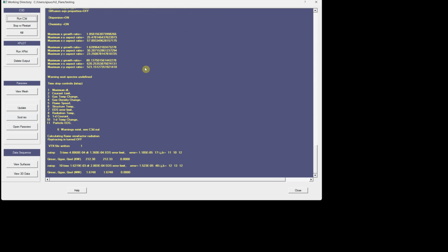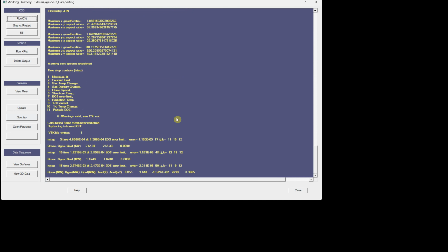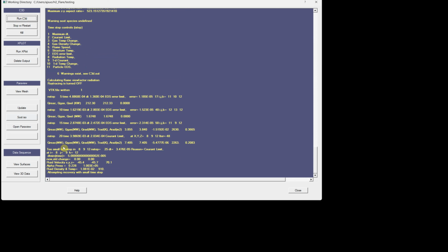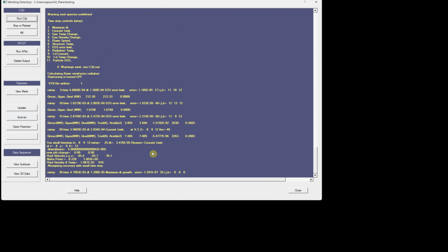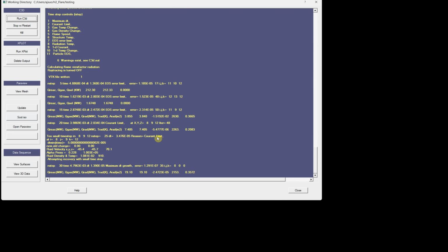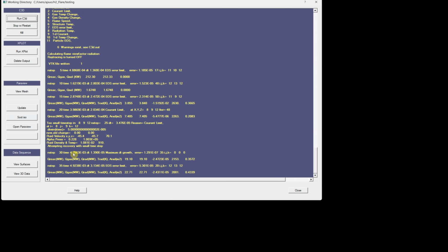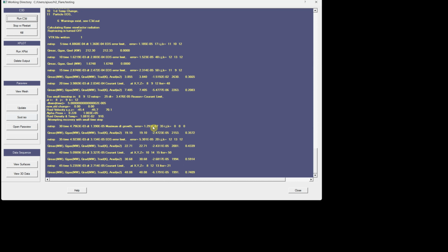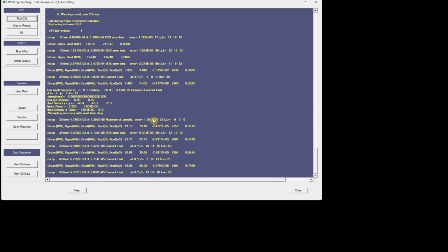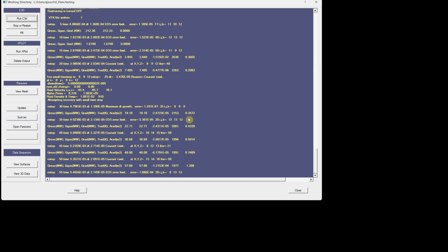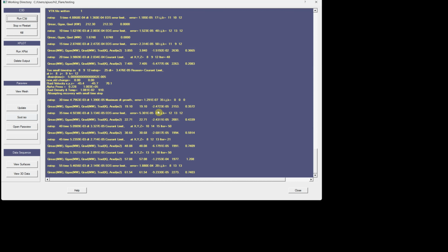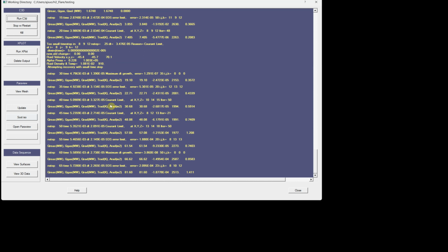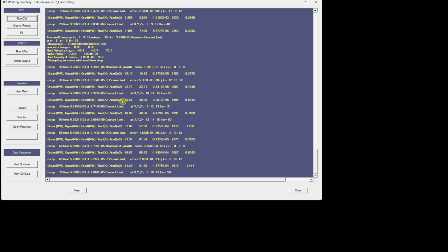As you can see, it's running okay. Well, let me describe the output a little bit. It shows you the time step. It's called end step. We got some high-speed flow going on. That's the Courant limit. Then this is the time. We have the growth, it's growing, and this is the error in the equation of state, and the cell number, its location. You can see it's either 0 or growing. Here the time step is growing. Here you go, the equation of state error limit. Here it's a velocity limit.